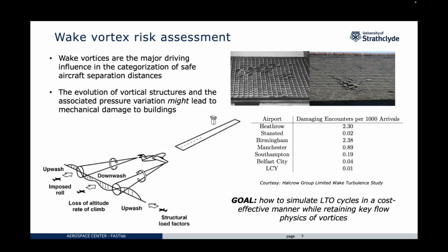These often occur, obviously, in regions where the traffic is condensed, so on final approach or takeoff, and it's incredibly dangerous at this point because pilots have very little reaction time and often even control authority to sufficiently outmaneuver the effects of the wake vortex interaction. And that's why we have the mandatory aircraft separation distances that have continued to be used today from the research that was done about 40 years ago.